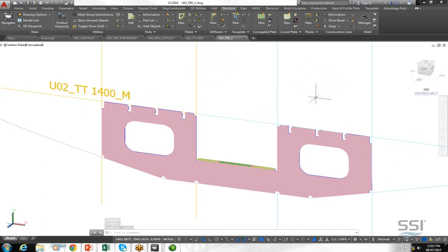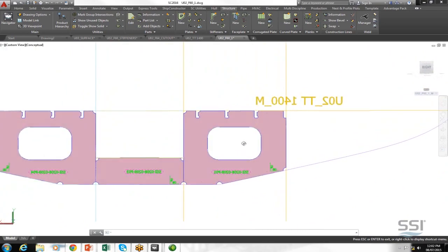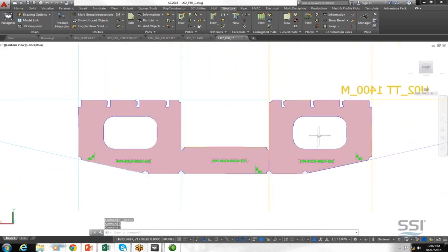So the last thing I want to do in terms of detailing my deck, my frame, the panels that we're working with here, is I want to add some stiffeners around the lightning hole. So I'm going to just switch around to the mark side of my drawing, and I'm going to use the same technique I used for the cutout. So our stiffeners are going to be based on construction lines, and the construction lines with stiffeners provide a path to extrude our profile rather than a boundary for our part.